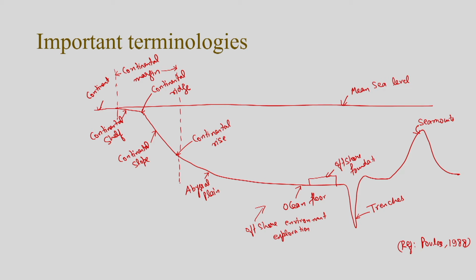Now, in order to ensure the safety of the foundation, very much similar to an onshore structure, you have to explore what kind of soil is there. So, the seafloor subsoil, because the material characteristics are changing very gradually or sometimes very rapidly. Second thing, water depth is there. Third thing, you also have to take into account a lot of processes happening between the ground surface and the water surface.